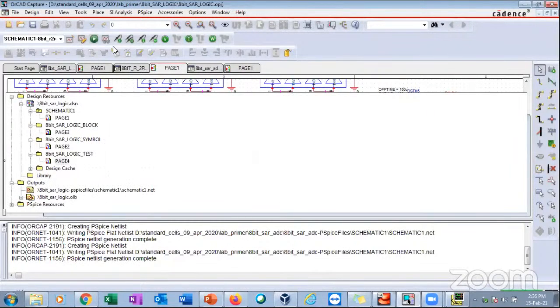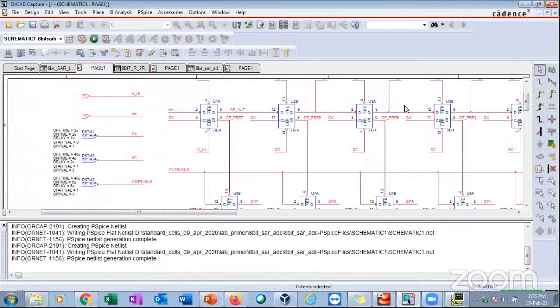8 different frequencies have been made use of. And if you look at the SAR, successive approximation register, we have made use of the D flip-flop, which is 7474. So these are ideal blocks that are already available, designed and tested ICs. By taking this as a reference, we are designing a practical circuit where the output can be anything. It might change based on the technology node values, so it cannot be exactly equal, but depending on the technology library, we have to check how it behaves.